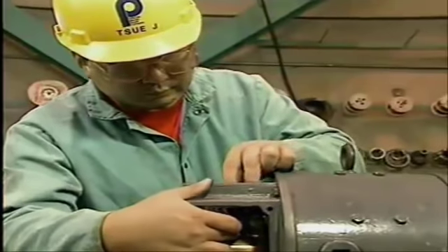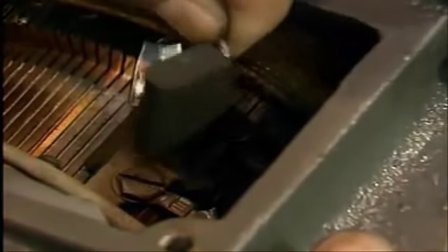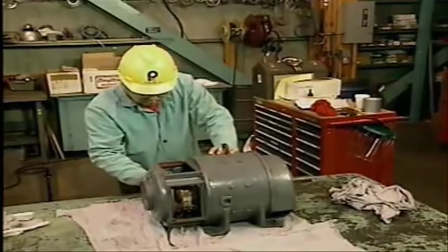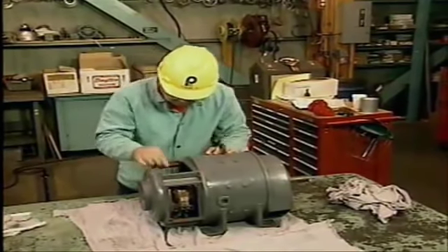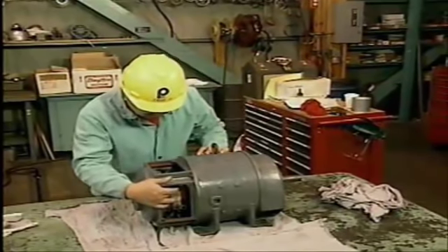The inside surfaces of the brush holders should be checked to make sure that they're clean and smooth. Any burrs or dings must be removed with a file or sandpaper. If they're not removed, a brush could get hung up on them and not make good contact with the commutator. The bottom edges of the brush holders should also be smooth, straight, and free of burrs. If they're not, the edges must be smoothed with a file or sandpaper, or the brush holders must be replaced. Most brush holders can be adjusted, so it's very important to make sure that they're positioned properly.